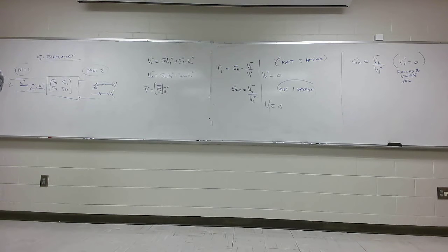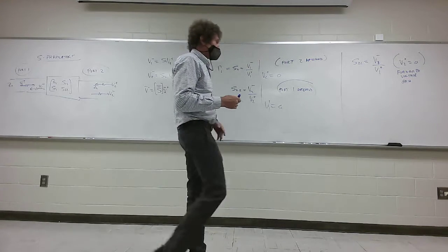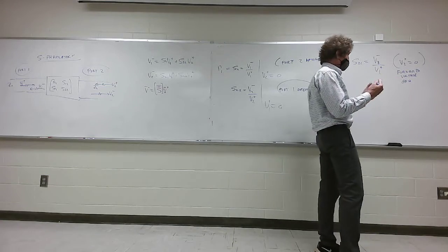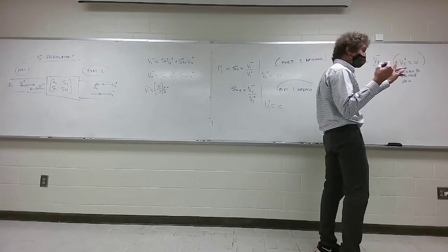But 2-port devices use S parameter measurements, and they'll show you S11, S22, S21, and S12 versus frequency. And that's real important. That's what you get on a data sheet. If anybody's ever buying components, when you get chips for high frequency work, microwave work, you'll see that on it. And they'll have a lot more information, but that's the primary, because you want to know what the voltage gain is on the range of frequencies you deal with.